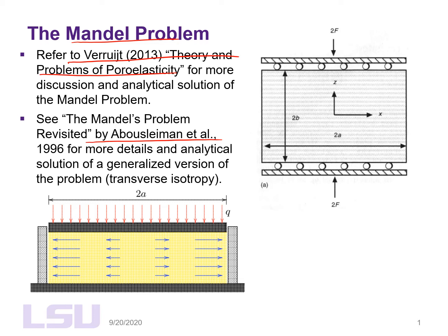You're applying stress instantaneously at the top through a roller, meaning you allow displacement in this direction, but you don't allow displacement in this. So u in this direction, which is x, is 0. Same at the bottom, but you allow displacement in this direction, right?